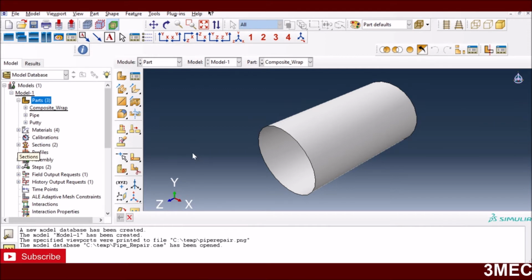Okay, so let's see how we can do that. Again, I'm not going to give you any dimensions since it was from someone else, so I'm just going to keep it as abstract as possible, but obviously the main aim is to show you the whole process of simulating similar problems. So first thing is to create a wrap. In this case the wrap was a kind of fiber reinforced composite which was wrapped around it and let it cure for some time. So I will come back to that, how I have provided the properties, but I'm modeling it as a shell.